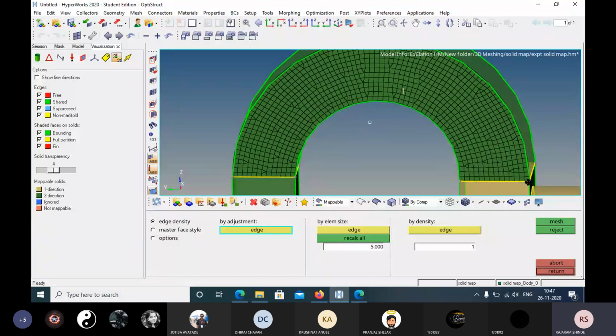Properties. Now here I will set the solid properties. Next, I will define the color as this one. Type is 3D, card image PSOLID. Material which we have created. Okay, and say create. Not necessary to do here. Created it. Okay. Now you have to assign the